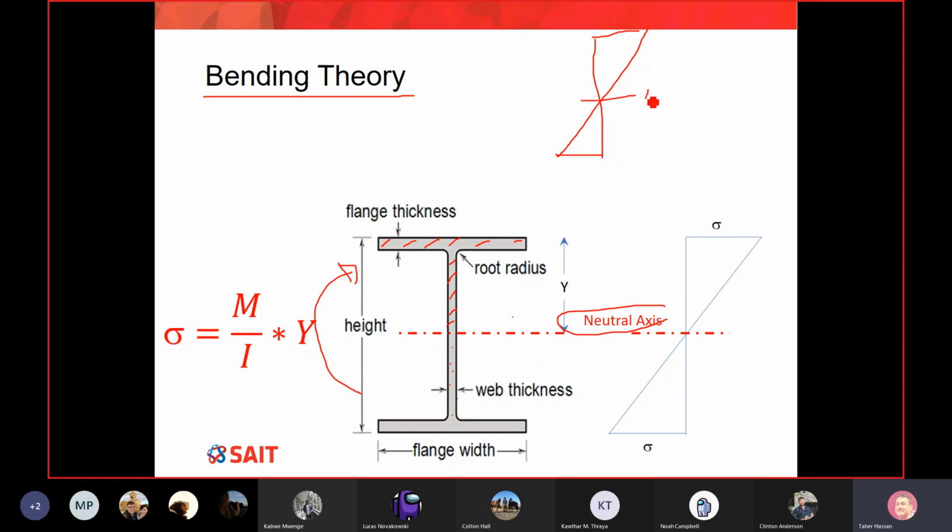So what does it mean? It means on the neutral axis there is no change, so zero strain here. And as you go away from the neutral axis upward, the amount of strain will increase. Where is the maximum strain? Any help? At the end of it. You can see here the maximum strain at the extreme fibers of the beam, which are the top and the bottom fibers. So this point here and this point here have the maximum strain.